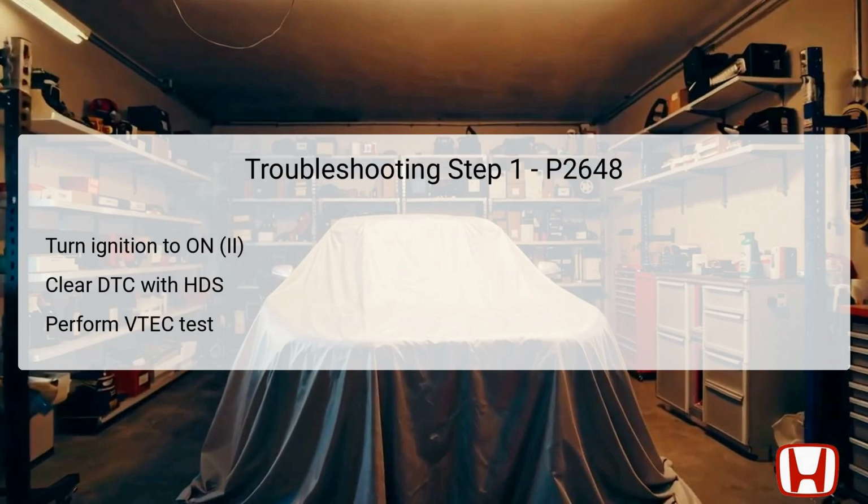The first step in troubleshooting DTC P2648 involves turning the ignition switch to the on position, designated as II. This action powers the vehicle's electrical systems without starting the engine. Next, the diagnostic HDS, Honda Diagnostic System, should be used to clear the stored DTC from the system.